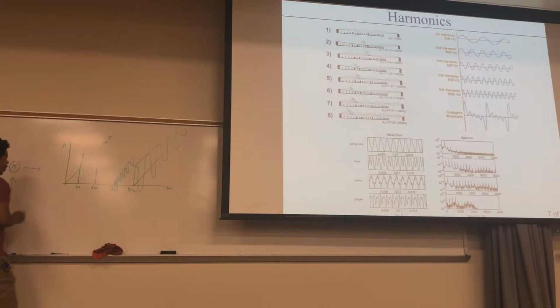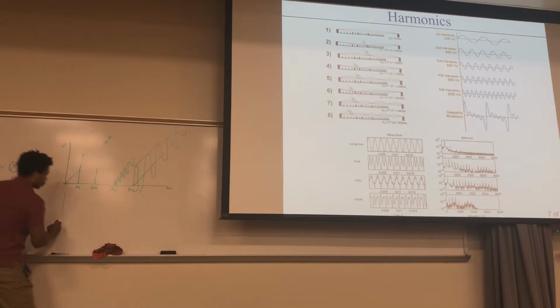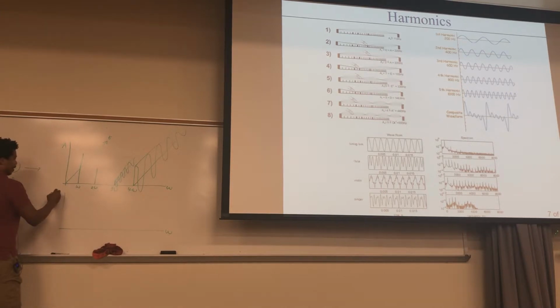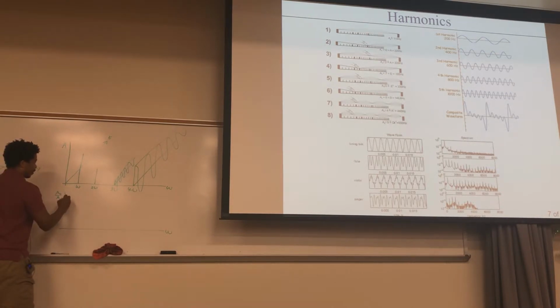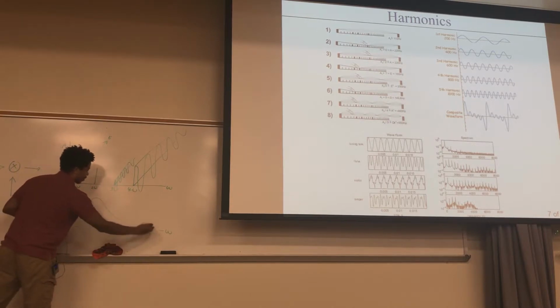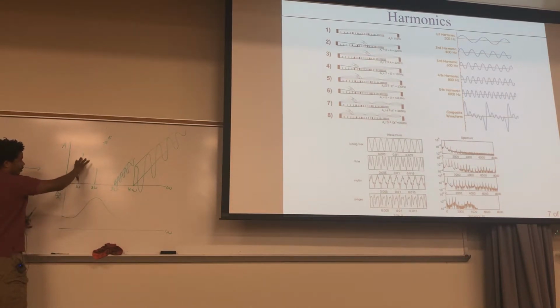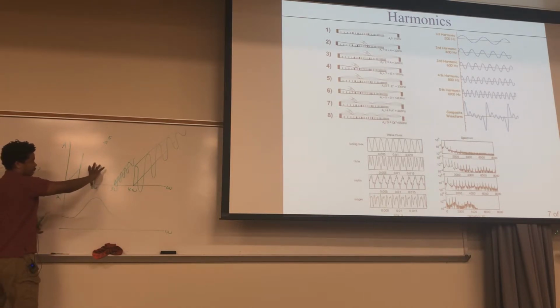Now, of course, when we do a Bode plot, and you have this frequency here, now we're looking at gain, so output over input. And now when we send it through something that looks like that, whatever our Bode plot is, this amplifier, certain of these harmonics are going to be attenuated, some are going to be amplified.